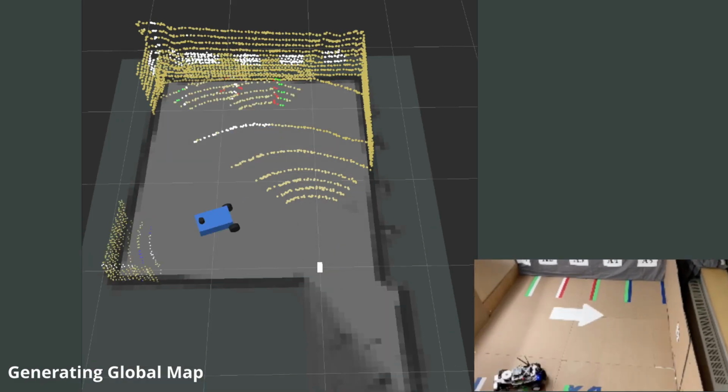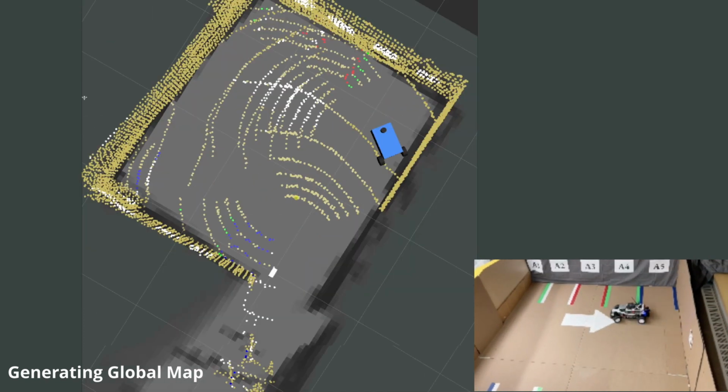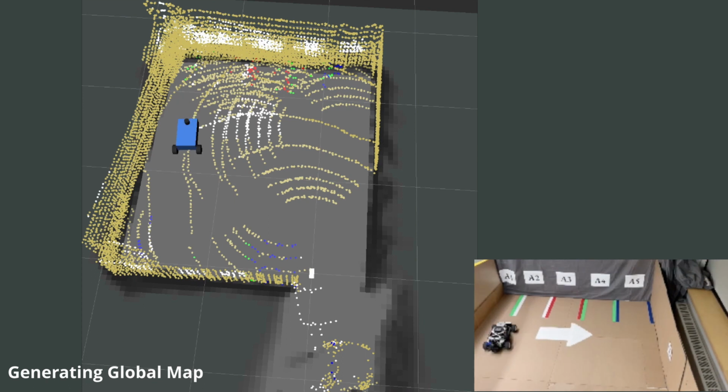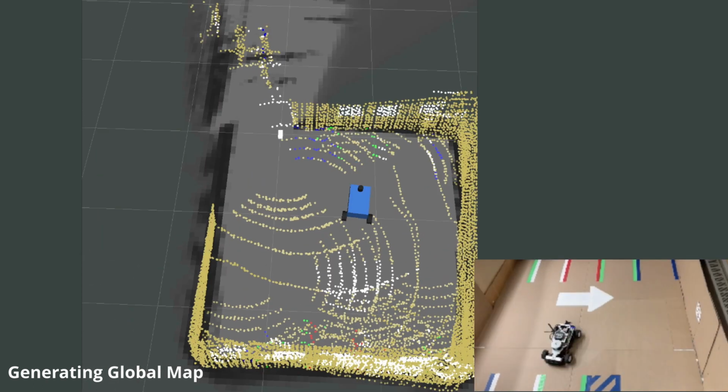These labeled point clouds are then stitched together to create a cohesive map using the ROS laser assembler service, which places all the point clouds in the frame of our overall map.